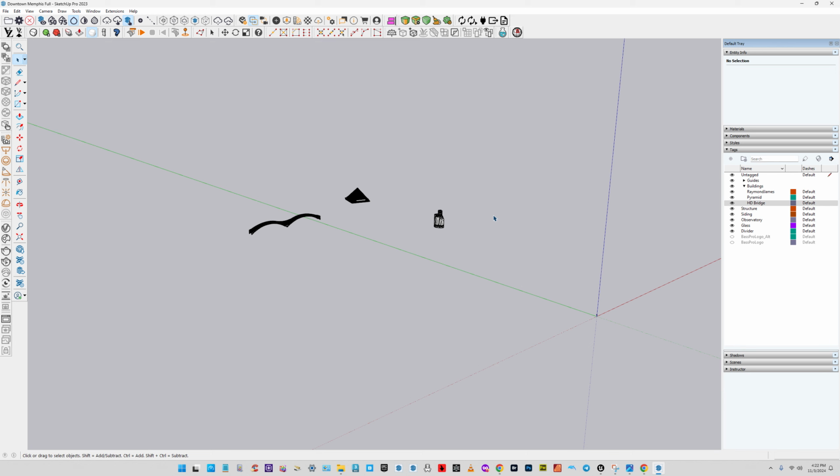That is going to be exactly where your model needs to be. It's going to import exactly where the model needs to be at the scale it needs to be. Export the OBJ file from Unreal Engine, import it into SketchUp, and then figure out how to move those assets into place using the STL file location as a reference.